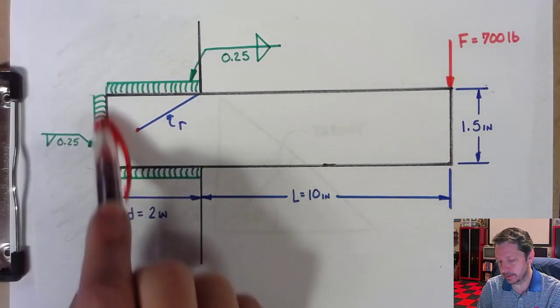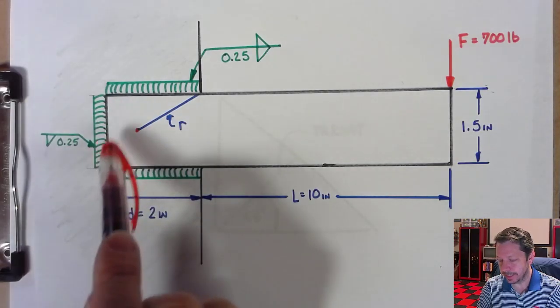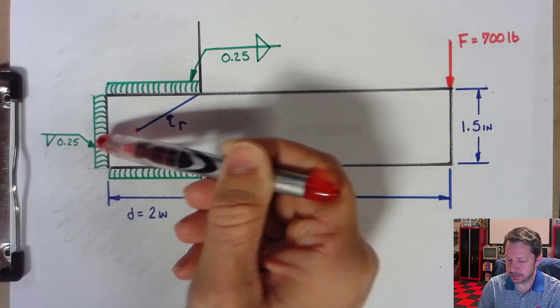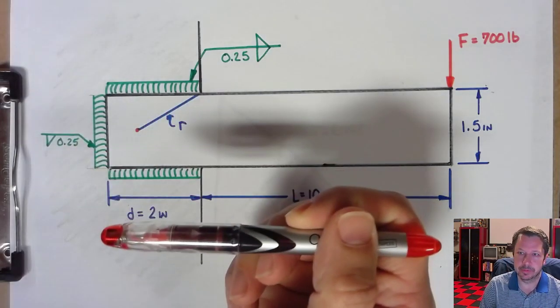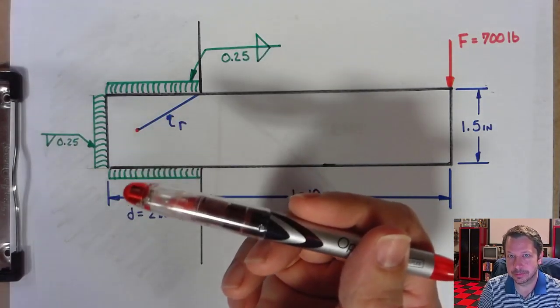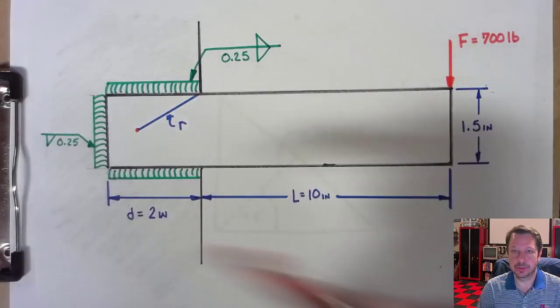on the arrow side of where it's pointing. So it should be pointing to this line. I just didn't draw it there because it got cluttery with everything on top of actually drawing the weld on the picture. Normally you don't draw the weld on the picture.